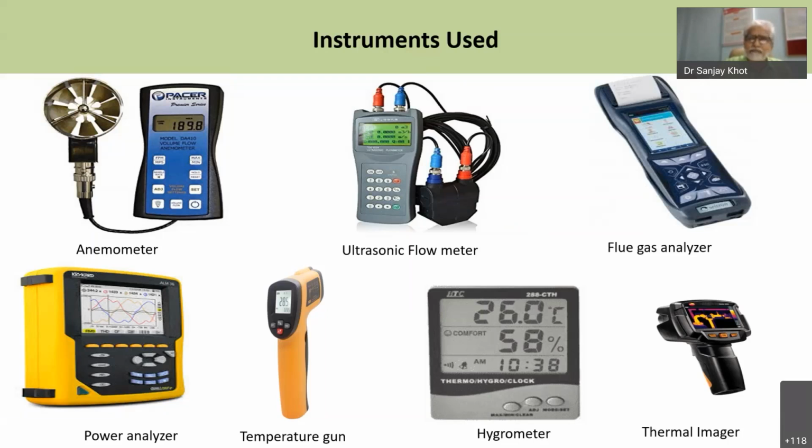Now this is an anemometer, which is used to measure the flow of fluid. Generally it is used for the flow of air in air conditioning systems and humidification plants. In pharmacy, you can also use anemometers to measure in most of the ducts, because in pharmacy you need to control and monitor air quality as per the requirement of the particular product being manufactured. Here we get an idea about the velocity of the air, and then we can calculate how much quantity of air is flowing.